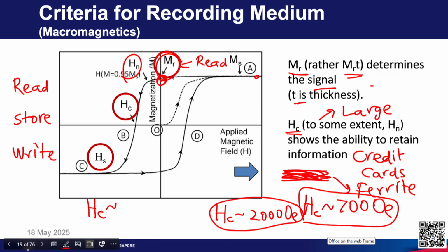Okay, so before the mic was off, I was talking about coercivity being large enough or not enough to retain the information. So, in the old credit cards, the coercivity is small. So, a magnet that you keep in your pocket may be able to erase the information. On the other hand, if you take any contemporary hard disk drives, the coercivity is around 6000 oersted. So, you notice that this value is much larger than the field generated by the magnets, which is around 2000 oersted.